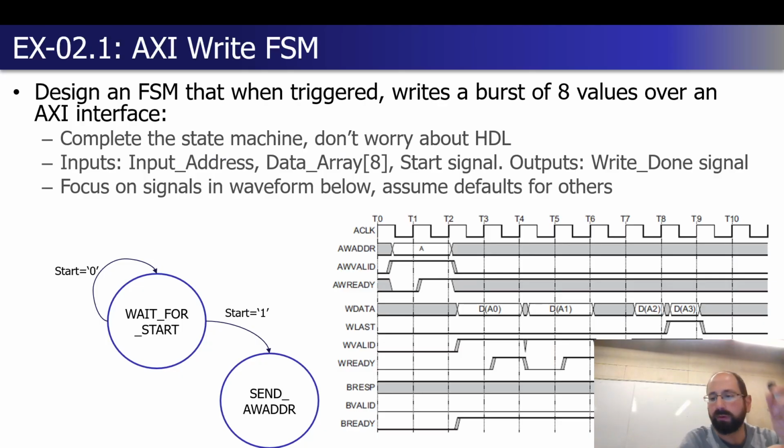Questions about that example? It's not perfect. It's obviously not the entire VHDL for what we need to do here, but that's the mental model of interfacing with an AXI memory map or the full AXI interface here. There's a couple, and it's complicated, right? There's a whole lot of signals in your design. This diagram doesn't really show the full of it.